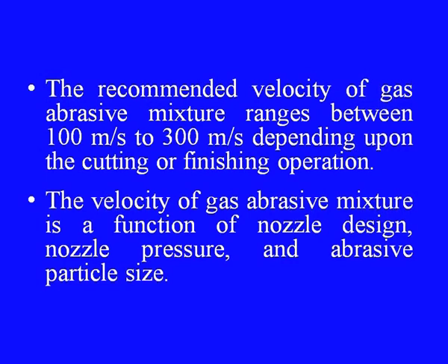The velocity of the gas abrasive mixture is a function of nozzle design, nozzle pressure and abrasive particle size. Further, standoff distance, also called SOD, is a very important parameter in this process. The standoff distance is defined as the distance between the nozzle tip and the work surface.